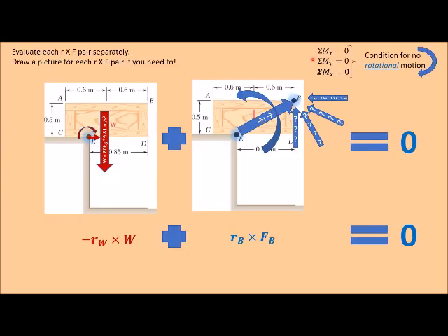So just like we add forces together to get 0, in Chapter 2, we're going to add moments together to get 0 to maintain static equilibrium as well. And remember, the moments are a vector, just like force is a vector. The only difference is the vector for moments is describing the axis of rotation versus the vector for forces is describing the direction of the force.